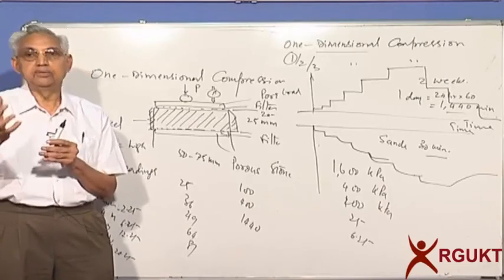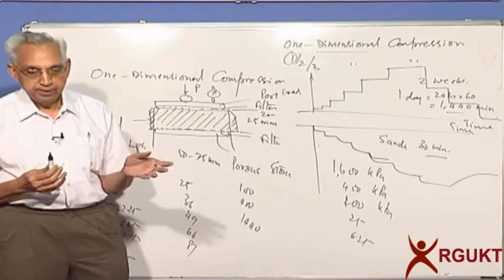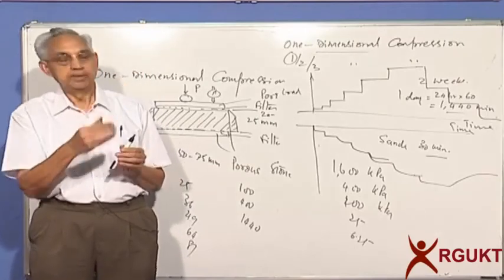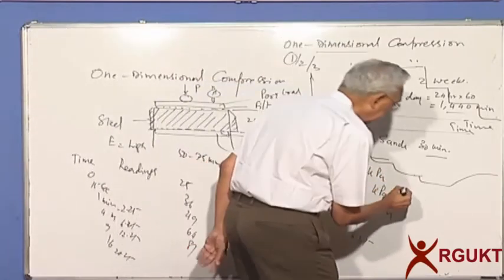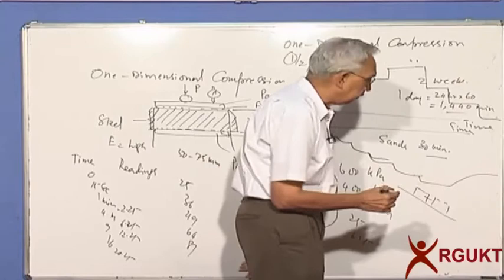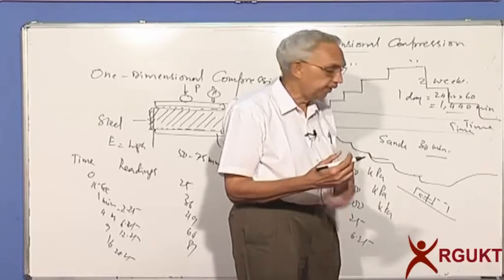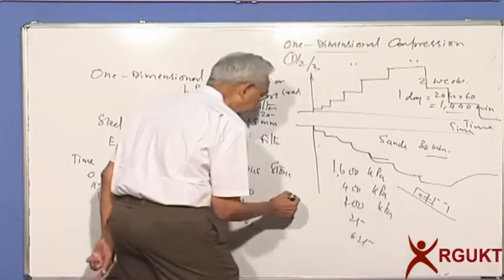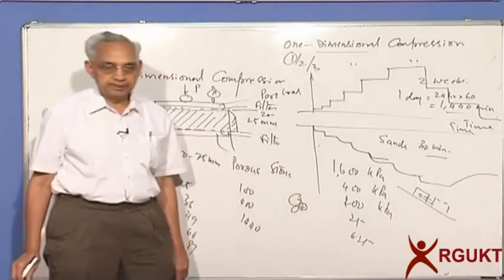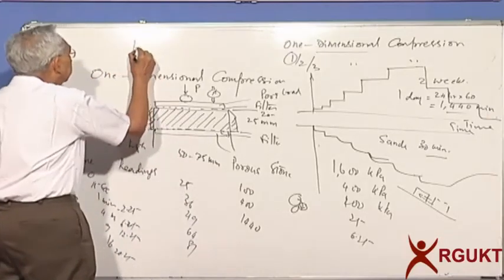Elastic compression, yes, you know that elastic means these deformations are recoverable. But when you have sliding and rotation, obviously it cannot slide up. Anything that moves down, imagine you have a slope and a particle has gone down. How can you expect it to move back just because you removed the load? There will be friction again, and the same thing would happen in terms of rolling also. It has come down to a more stable position, it will not roll back. So usually soils are inelastic.